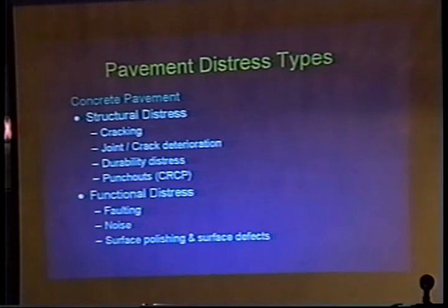But as the loads go over that, you start getting movement. It starts out real small, but as it goes through its life and its repeated cycles under heavy truck loading, you can get a lot of movement in that slab, and that's where you're really starting to lose your aggregate interlock. That's a problem. That'll cause deterioration at that joint or that crack.